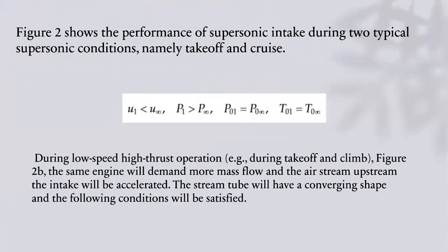Figure 2 shows the performance of a supersonic intake during two typical supersonic conditions, namely takeoff and cruise. So u1 is less than u infinity, and p1 is greater than p infinity, and p01 is equal to p0 infinity, and T01 is equal to T0 infinity.